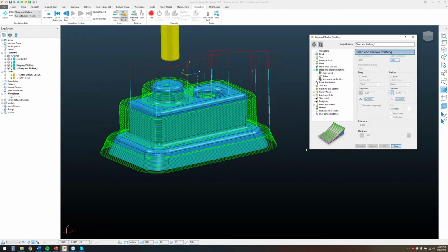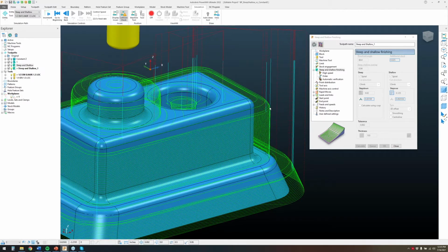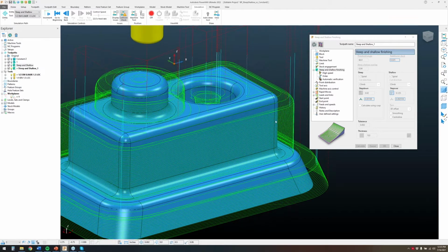And this is where you actually see that threshold angle. So the step over, when it was 20 thou, totally fine. You were good to go. But you can see with that threshold angle at 60, it's taking that 3D offset and it's expanding it further down, and you're utilizing almost more than you should. You want to shrink up that threshold angle actually a little bit.